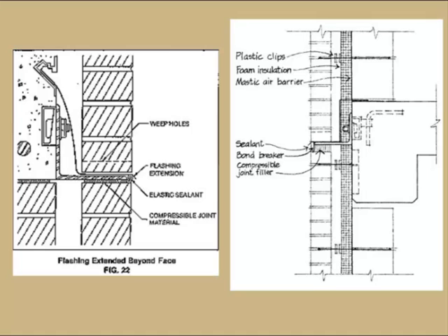That is the flashing that we're talking about, that carries any moisture that's inside that cavity down and then out through a weep system. On the right-hand side, you can see a similar situation. That kind of crosshatch section there shows there is an insulation board. It's important to make sure that your flashing still accommodates that and is continuous to prevent water from backing up through that detail.